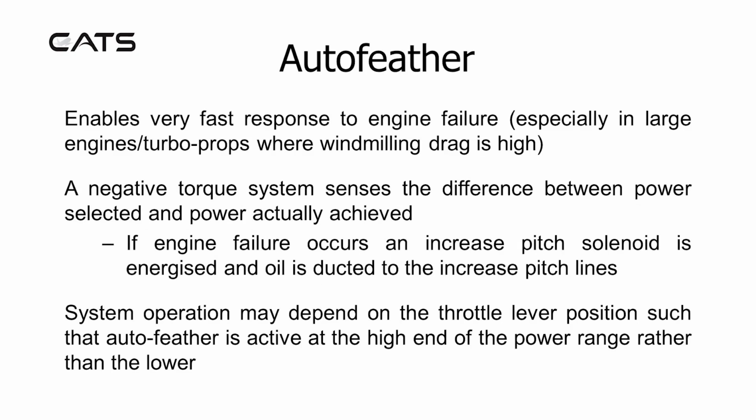Autofeather. This enables very fast response to engine failure, especially in large engine turboprops where windmilling drag is high. A negative torque system senses the difference between power selected and power actually achieved. If engine failure occurs, an increased pitch solenoid is energized and oil is ducted to the increased pitch lines. System operation may depend on the throttle lever position, such that autofeather is active at the high end of the power range rather than the low end.